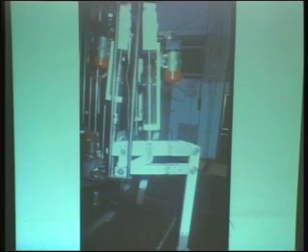Now we have used the ball screw there. Ball screws have limited life depending on the load, just like a ball bearing has limited life depending on the load and speed of operation. So maybe once in a few years we have to replace those ball screws. So that's the way the design has been made. So this is a mechanism which converts the rotary motion of the servo motor into the useful motion of my leg.